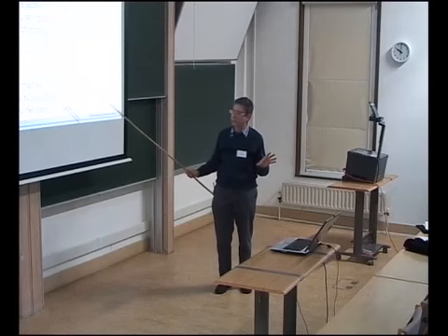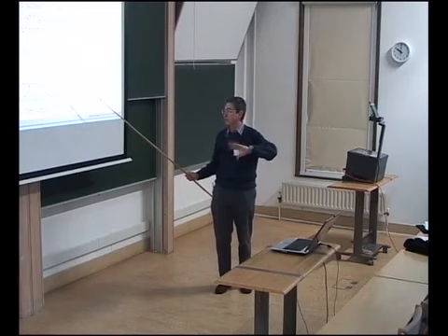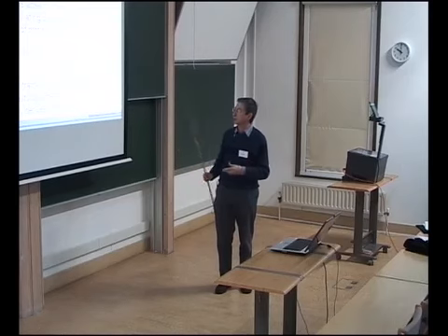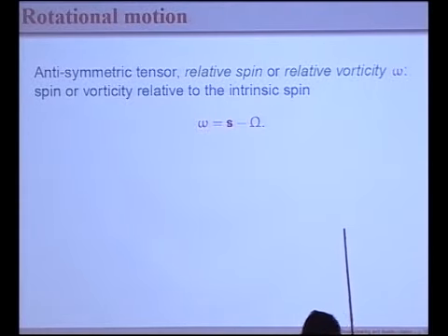Notice that omega 3 being 0, somehow this is a rotation, but this is a continuum model, so we're talking about averages. So it's not saying that the grain rotation is 0, but merely it averages out to 0. So if a grain is rotating clockwise, then a neighboring grain may be rotating anti-clockwise by an equivalent amount. So somehow this is an average grain rotation of 0.